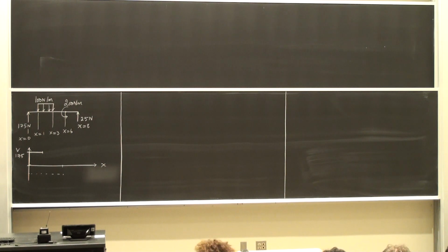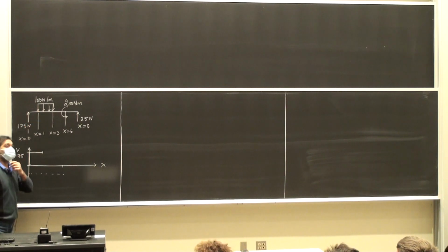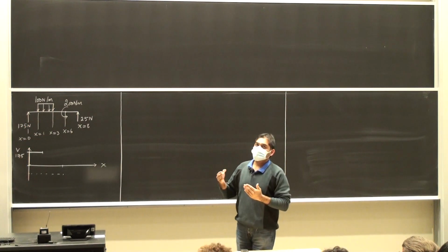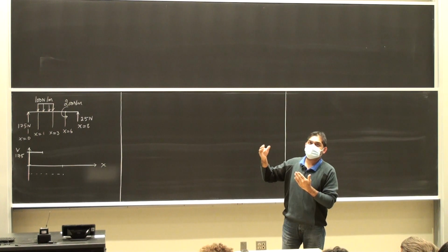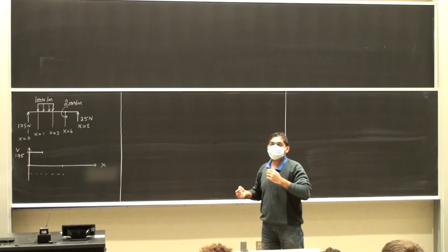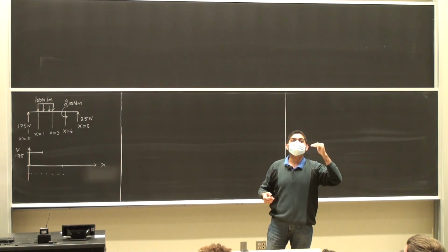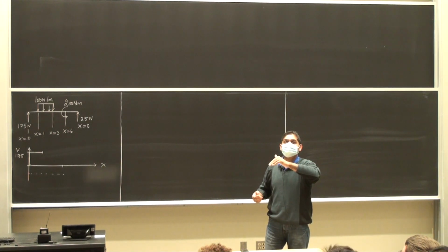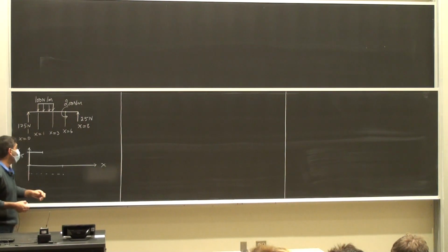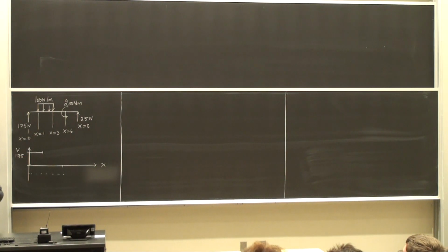So how do I go from 175 to minus 25? The slope of the shear force diagram is equal to the load intensity. The load intensity here is constant and negative, which means that the slope of the shear force diagram is going to be constant and negative. So I'm going to have a linear or a straight line motion from 175 newtons all the way to 25 negative.